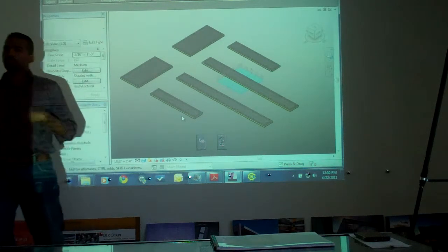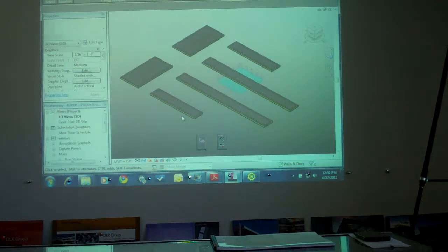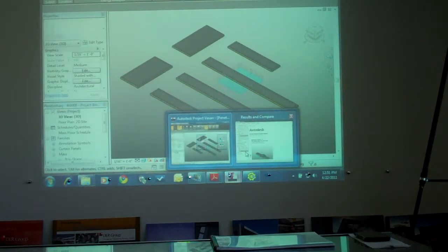So it automatically puts that information in based on what you define in that little dialog box. So it's because you decided it was a penitentiary, it added skylights. Well, I asked it to. I asked it to add 3% of the roof to be skylights because I assume most of the penitentiary was skylights. So you can play with these numbers and see how much of an impact it is.